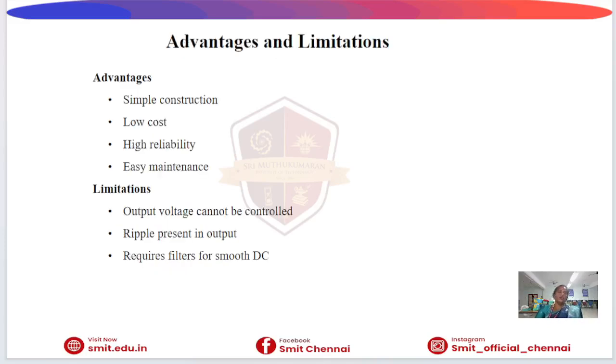Now let us discuss the advantages and limitations of uncontrolled rectifiers. The major advantages are simple construction, low manufacturing cost, high reliability, and easy maintenance. Since diodes are robust devices, these circuits have a long operating life and require minimal maintenance.